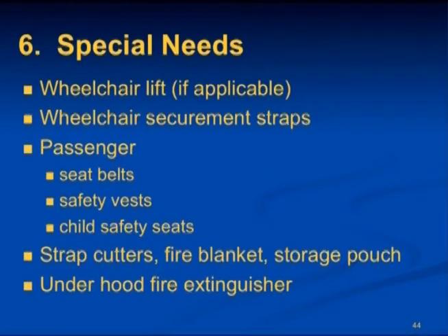Okay, at this point in your pre-trip, if you have a special needs bus, this is the time to check your special equipment. So let's take a look at that. If you drive a bus equipped with a wheelchair lift, pay special attention to the compartment for anything out of the ordinary. The lift door should operate smoothly and latch securely.